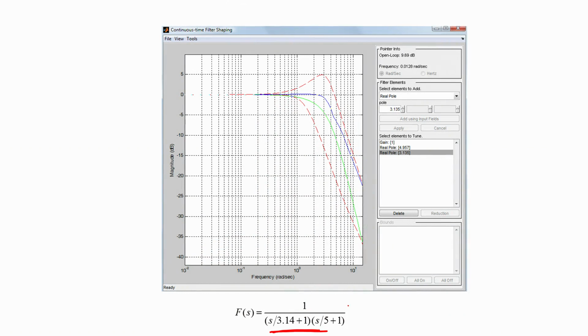We note that exactly as in the case of the root locus design, the pre-filter has unity DC gain, and for this particular pre-filter structure we note that both T upper and T lower are within the permissible limits as specified by these upper and lower red curves.